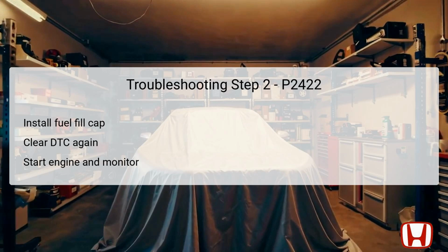Ensure that there is no load on the engine, which can be achieved by placing a continuously variable transmission, CVT, in P or N, or if it's a manual transmission, put it in neutral. Allowing the engine to idle ensures that the radiator fan activates and maintains proper operating temperature, while you monitor the EVAP purge control duty around 3000 RPM with the HDS, taking note of duty cycle values to validate whether the